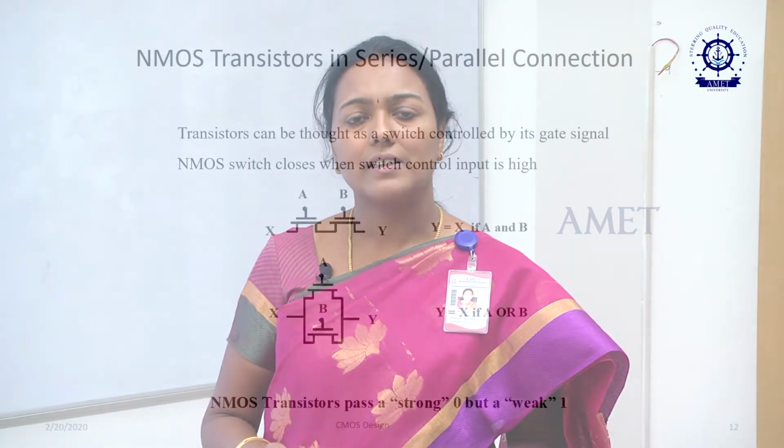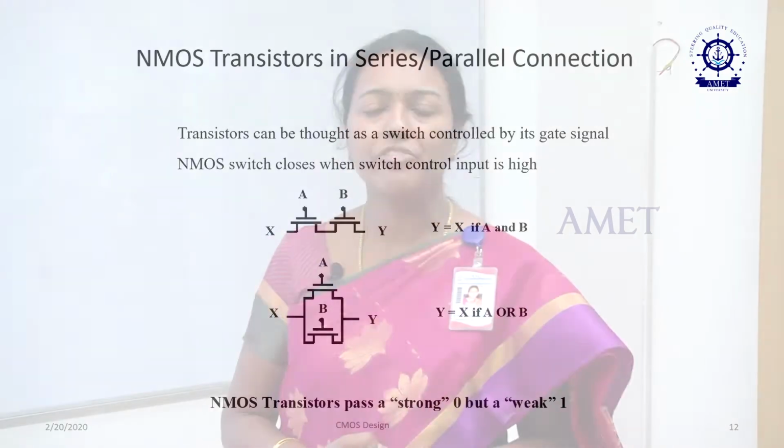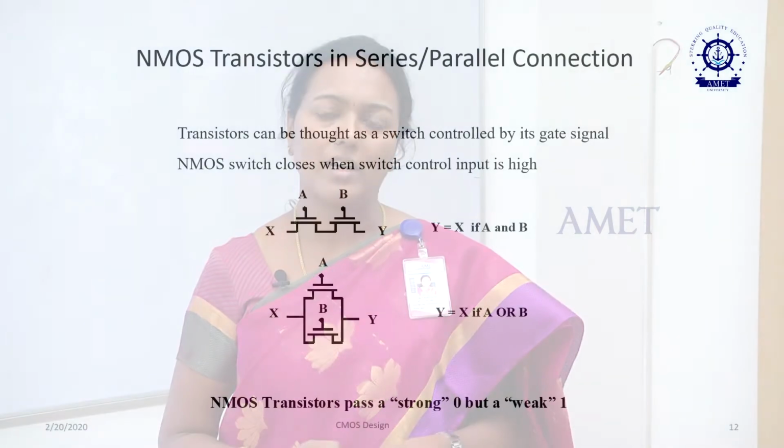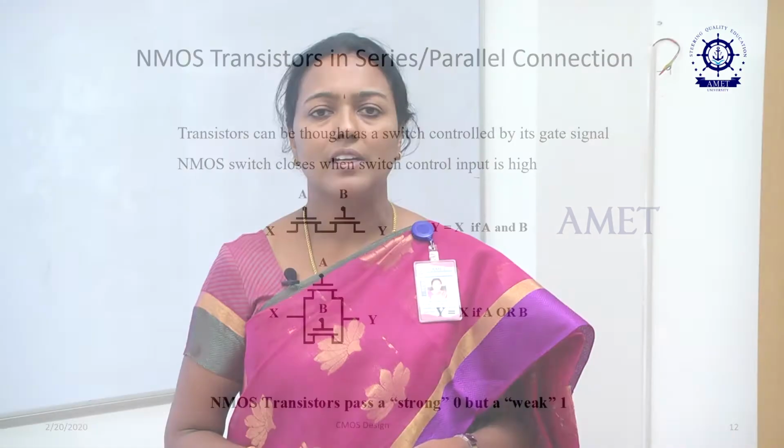Here the MOS transistors which are connected in series as well as in parallel are shown for various gates. Say for example, for a CMOS inverter, there must be one PMOS transistor at the upper half of the structure, and one NMOS transistor at the lower half of the structure. The gates of both the transistors are tied together and a common input is given to the gates.